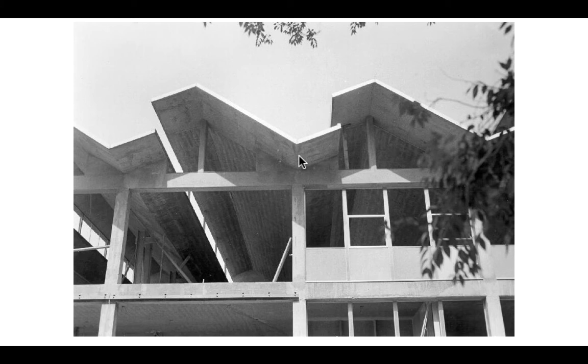And structurally, the plate doesn't really care what shape it is, right? The efficiency is just about reducing the amount of material that we need. All the plate kind of feels is that it's got a compression area there, a tension area there, a web in the middle that handles the shear between the two. So it's happy, right? It is going to work as a beam. Maybe somewhat limited in its length, the shallower it gets, but it's going to work as a beam, right? It has enough depth to carry a load over a span.